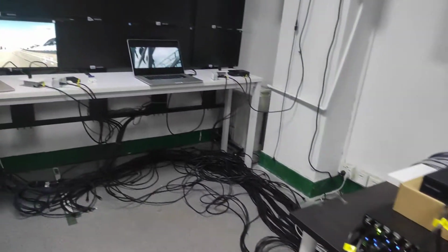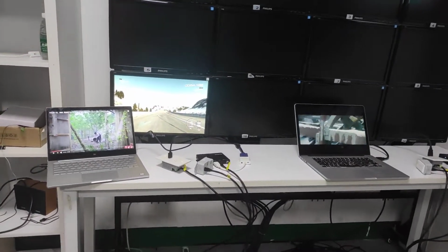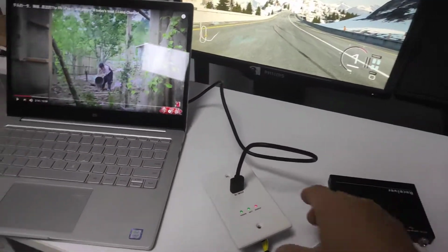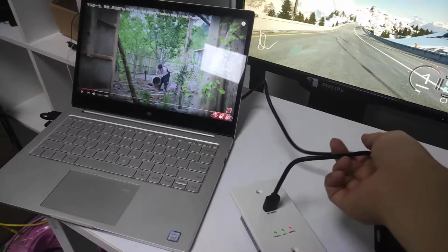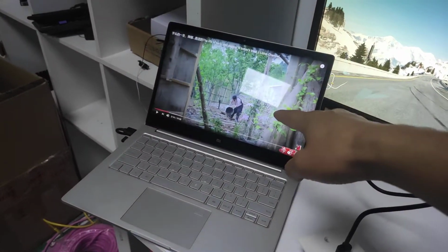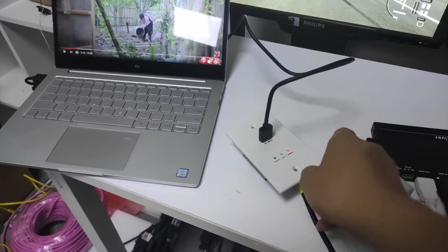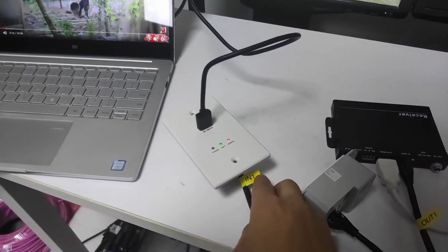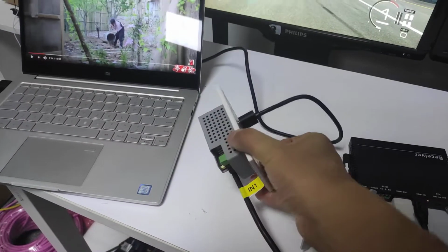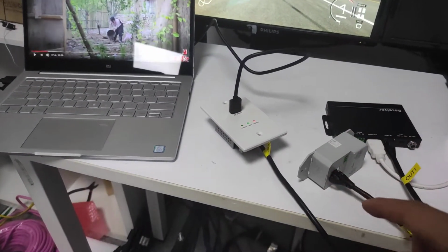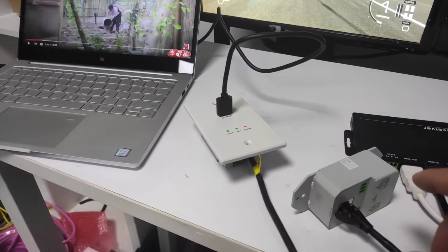If we go along the way to the two workstations on this side, here we have workstation one. Basically we have an HDMI Wallplate. This is the HDMI cable from this Windows laptop. Then we have this LAN cable, which is for input one. For this Wallplate, we don't need an extra power supply because we can get power over the Cat6 cable from the matrix switcher.